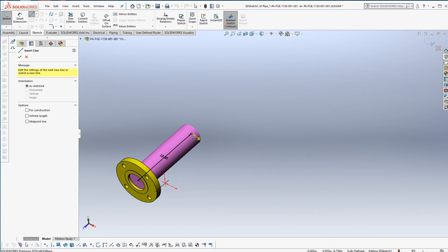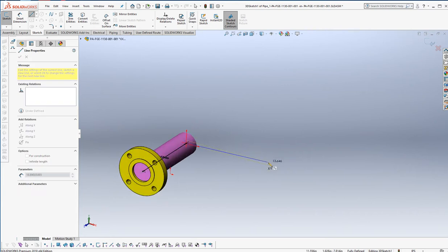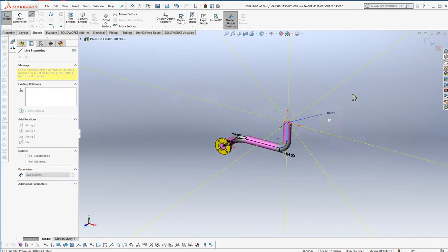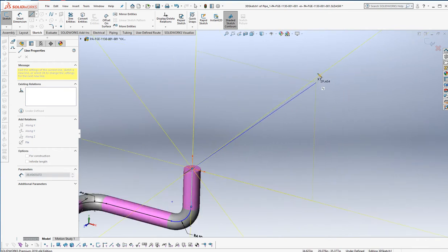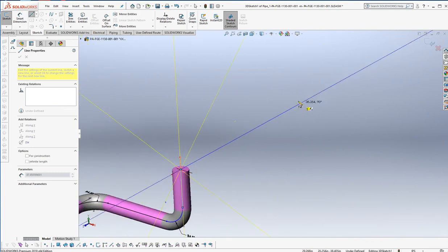We touch here and we come across. Now this works just like when we made that chair profile. So on the chair profile, we're going to go over 24 here roughly. So get it rough. And then we're going to go up 12 roughly. And then we're going to shoot over to the right. Am I shooting over to the right now? No. Check this out. I'm on a wall. So I need to hit tab. And now I'm coming the right direction.